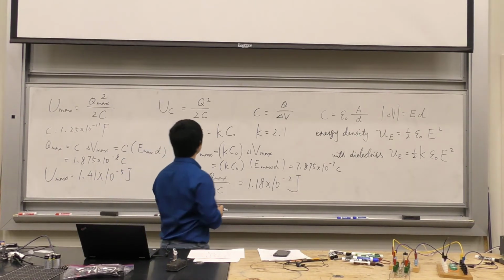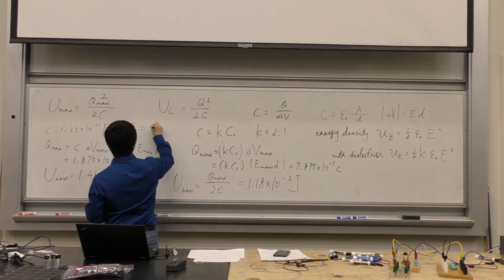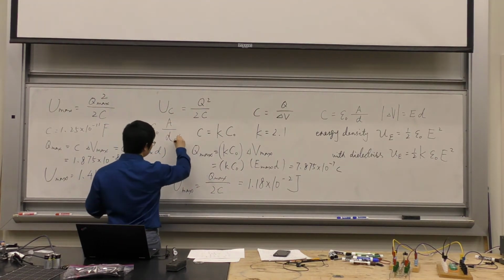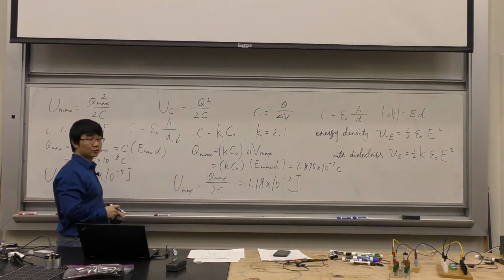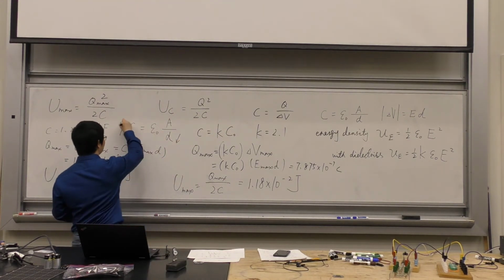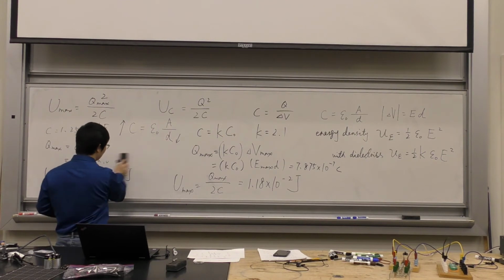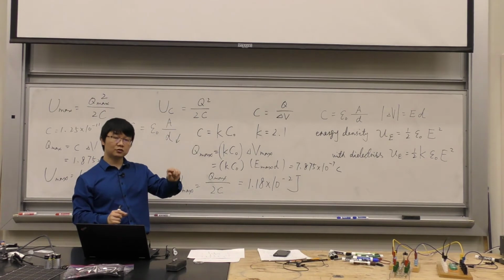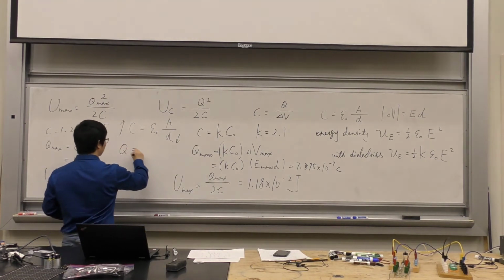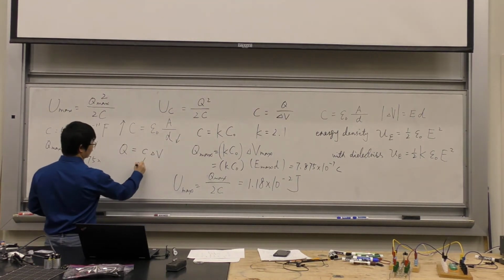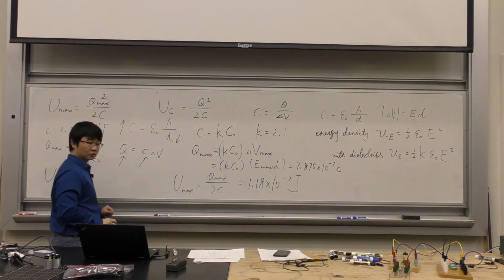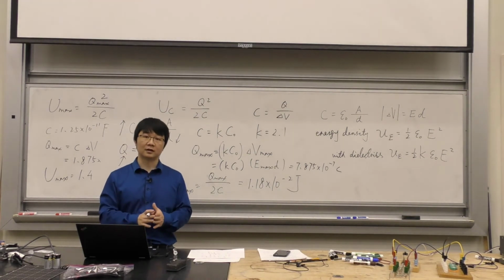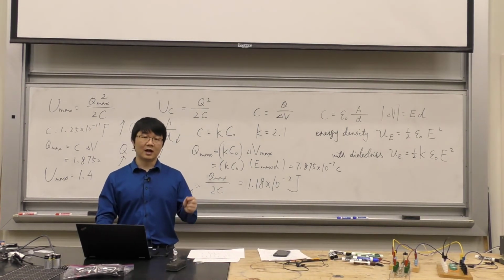I know that C equals epsilon naught times A divided by D. So you're reducing the distance between these two plates, and C is going to get larger. Say these two plates have a certain voltage. If C gets larger, the charge on the plate is going to get larger. So some charge moves really quickly underneath this key every time you type it.